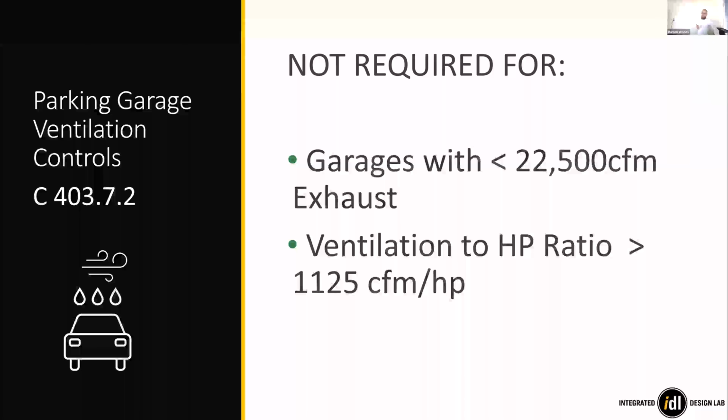IMC requires a minimum ventilation rate of 0.7 CFM per square foot. So doing some quick math, I should have put it directly on the slide: if you have a garage with 22,500 CFM and it's meeting that IMC, it's basically a garage that's less than 30,000 square feet, then you don't need these controls. The ventilation is still required by the mechanical code, but you don't have to have these interlocking controls.